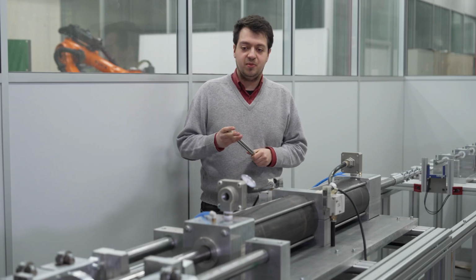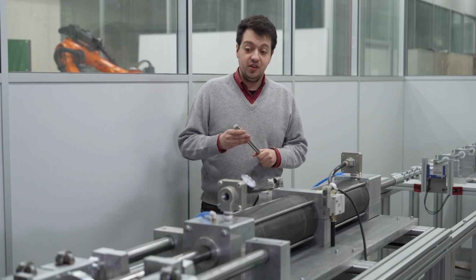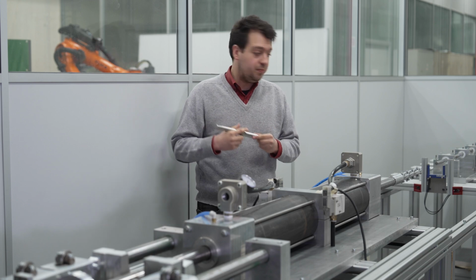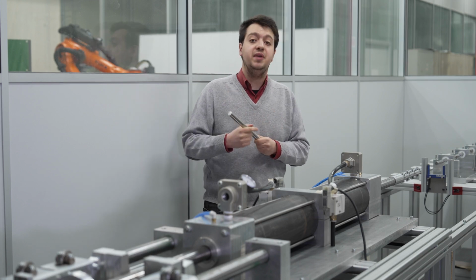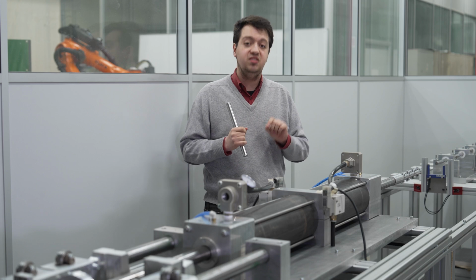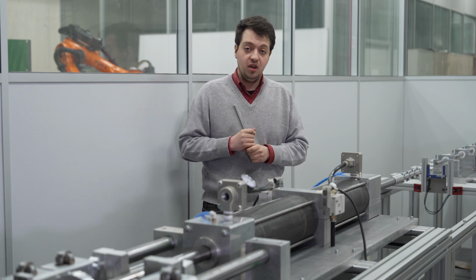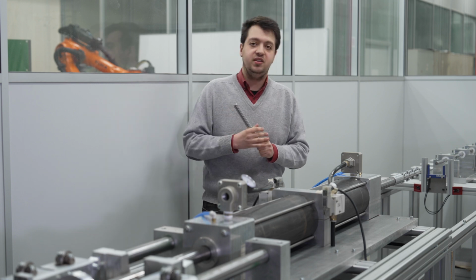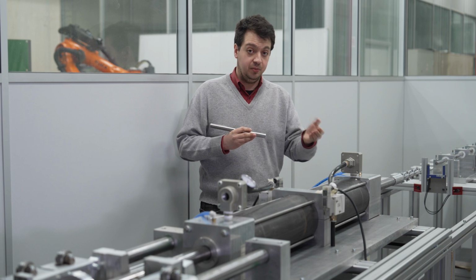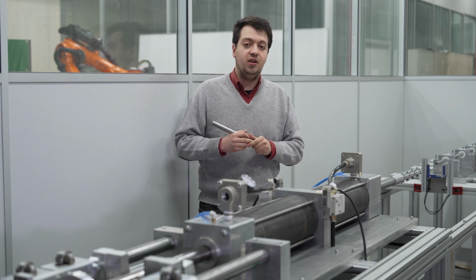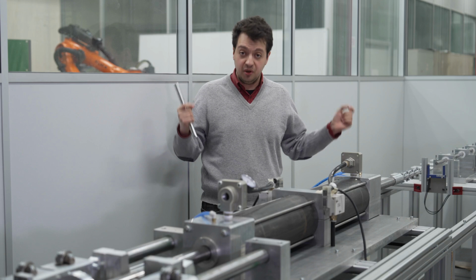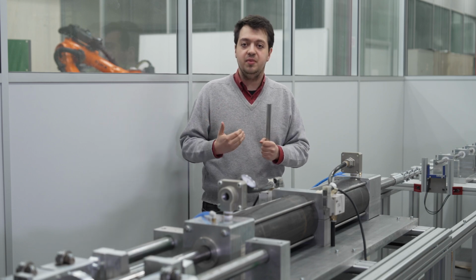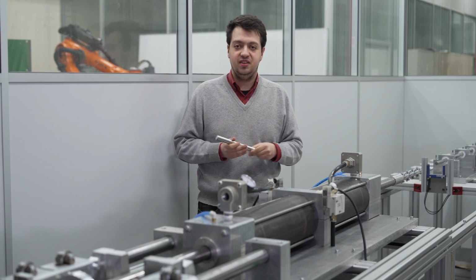A split Hopkinson pressure bar is a machine that tests materials at high strain rates. In it, an actuator launches a striker bar, which impacts an input bar, and during that impact, a stress wave is generated that propagates towards the material being tested. When said wave reaches the material, part of the wave is reflected backwards, and part of the wave is transmitted to the specimen of the material and to the output part. Strain gauges are placed in both bars and measure these waves. And with these measurements, we can estimate the behavior of the material being tested.